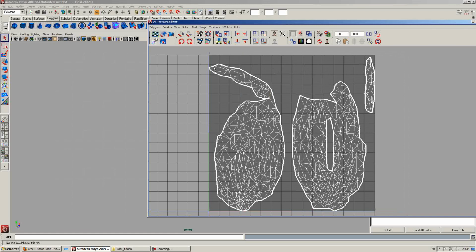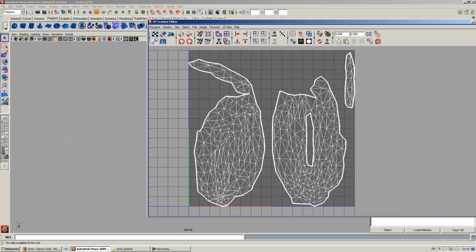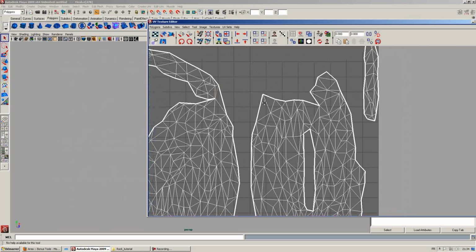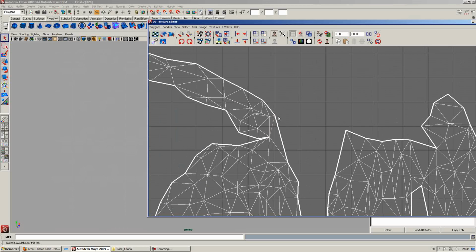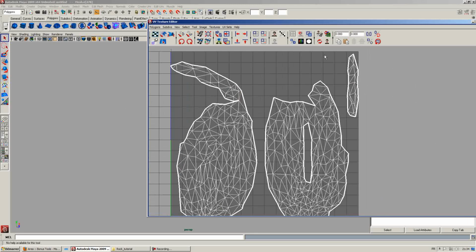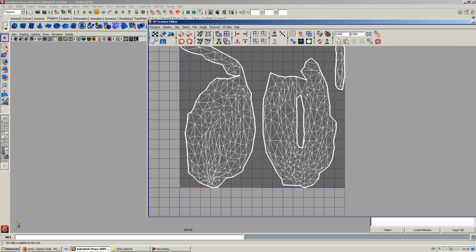So in this case, I have this part here. This really doesn't help if I want to fill the whole UV space. So it would be maybe more interesting if I cut this part out. That way it will allow me to scale this huge chunk here and have this part placed to fill in a gap or the spaces between the UV islands.